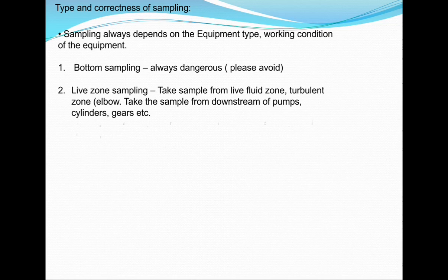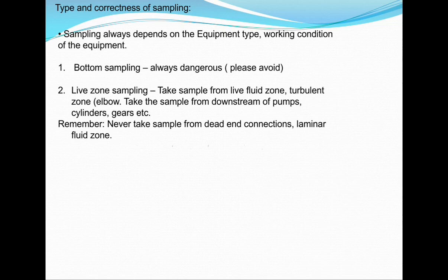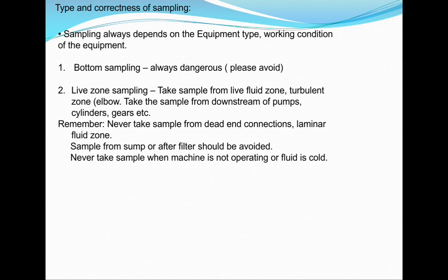And remember some points: never take a sample from a dead end connection. As I have already said, where there is a laminar flow, you should not take the sample. Where there is a dead end, it means there is contamination, you should not take the sample. And a sample from any sump or from the filter itself must be avoided. You should not take a sample from the sump and filter. Then never take a sample when the machine is not operating, or the fluid is cold. As I've already said, sampling is better if the equipment is in running condition.